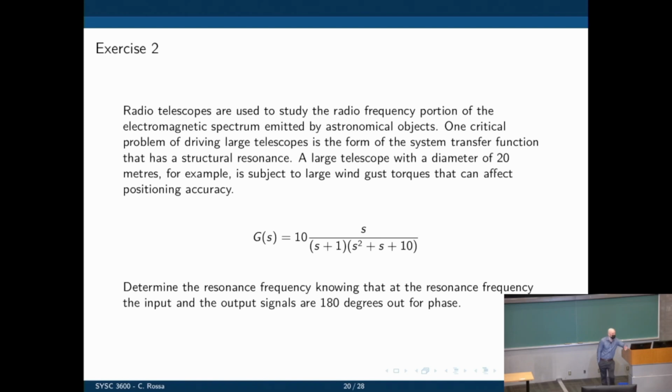As an example, we have a bridge, and that bridge had a dynamic resonance. Troops crossing the bridge had to slow down their march, because if they marched at a given pace, they would vibrate the structure at the resonance frequency. You're applying a force at a specific frequency, and then the entire structure would start to bounce and create a very large displacement. If they were running through, or if they slowed down, that wouldn't happen, because they are not at the critical frequency of resonance.